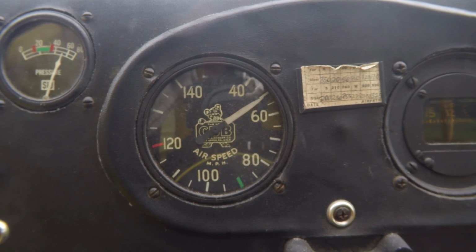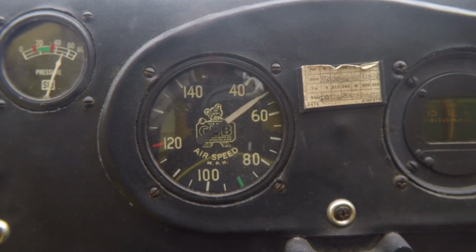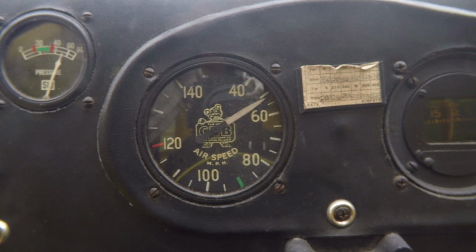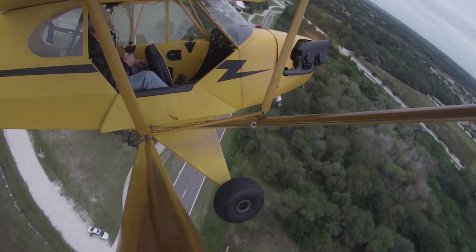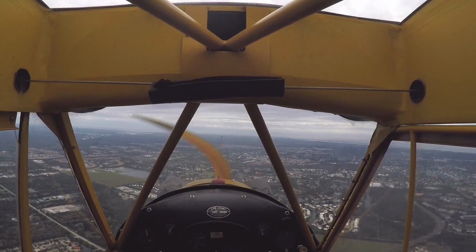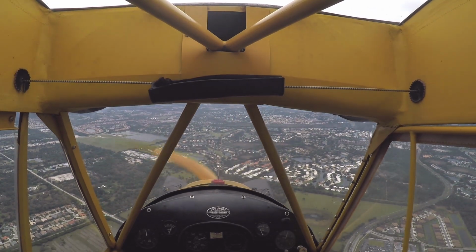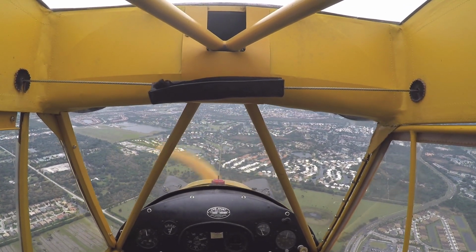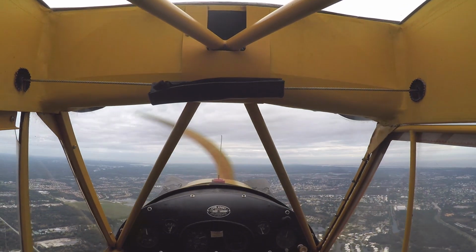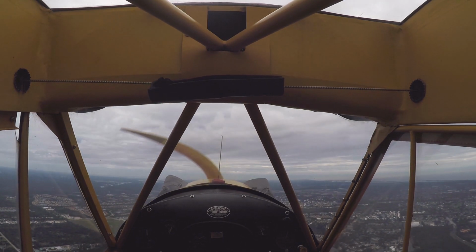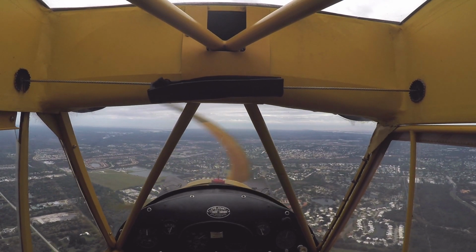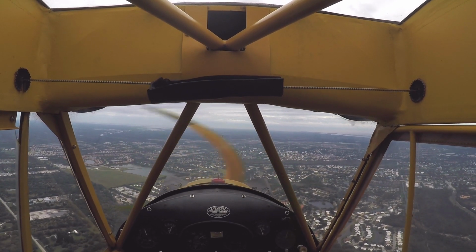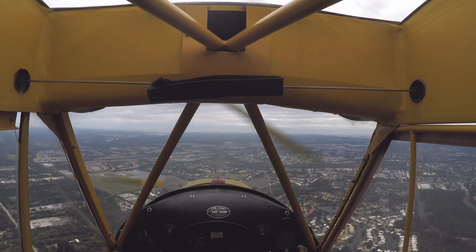Now in the Cub, I tend not to use the airspeed indicator that much because it's not very accurate or consistent. So I do what a lot of old tail dragger pilots do, which is to fly the wing, and that's another way of saying that I'm setting the pitch attitude by eyeball. I know, for example, that that's too low and my approach will be too fast, and that's too high and the approach is going to be slow and I risk a stall or a mush. But for most approaches, this is just about right. So that's the sight picture I'm looking for on a typical approach.